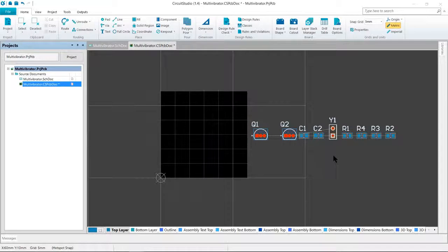The components will have been positioned outside the board, ready for placing on the board. There are a few steps before starting the component process, such as configuring the placement grid, the layers, and the design rules. As well as the layers used to fabricate the board, including your signal, power plane, mask, and silkscreen layers, the PCB editor also supports numerous other non-electrical layers, and the layers are grouped in the following way.